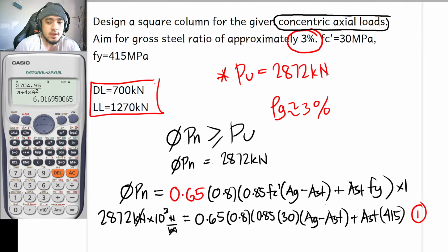So with that, guys, we are not to design this in shear. So once again, we are only required to put a minimum amount of lateral ties. So theoretically speaking, if we are only to be talking about its structural capacity, our lateral ties, we are actually not required to put.